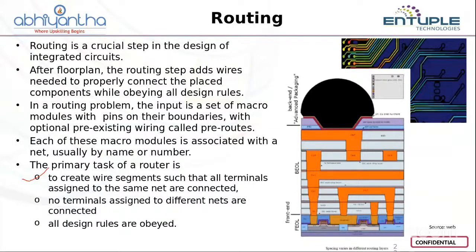After that, we can go for the routing process, and the entire routing depends on the technology node, either 90 or 45, or even if you go for lower technology nodes. Your routing will be very, very important. Your routing consists of various layers. The number of layers starts from metal 1 to metal 9, or in some technologies it goes up to metal 15.